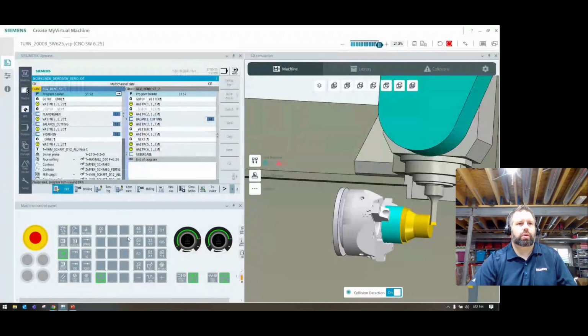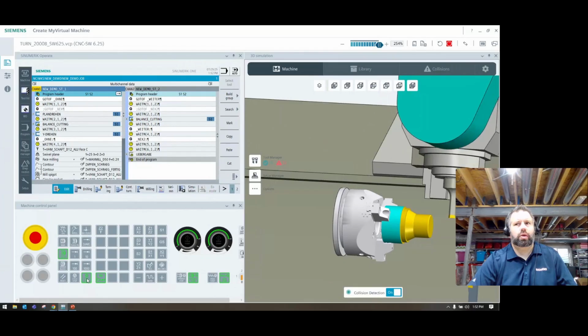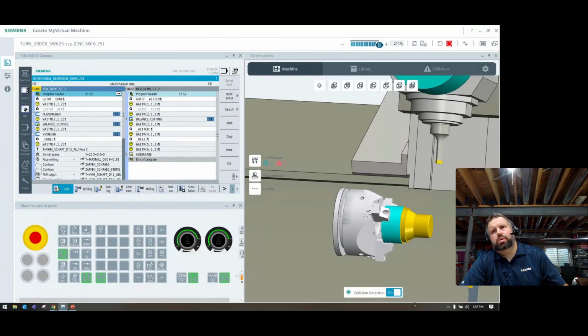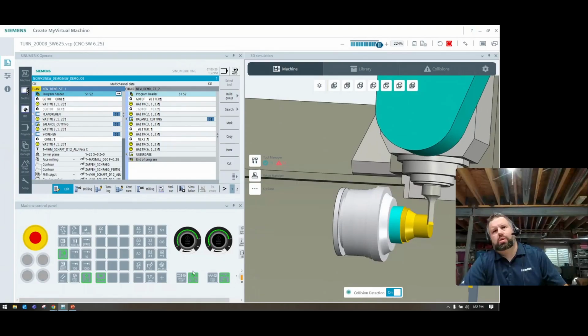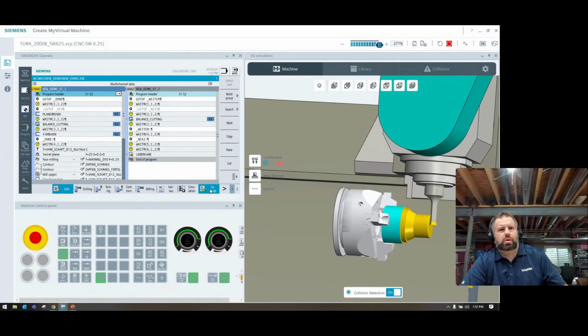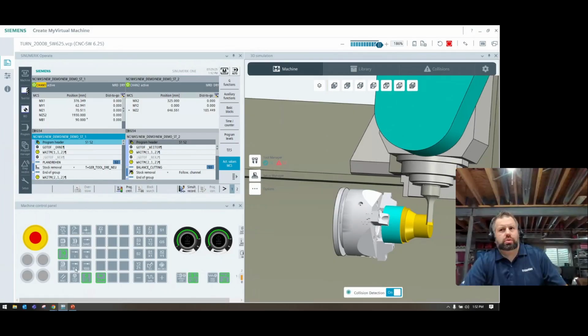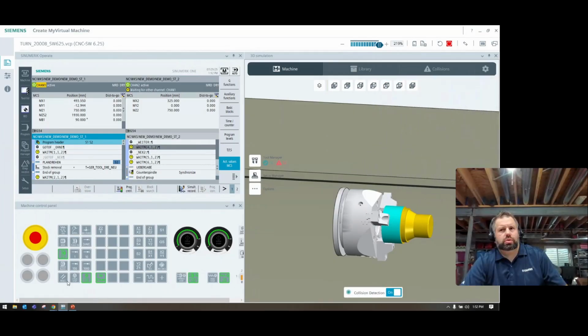While you're pulling that up, certainly some of the things that come to mind, boring head versus interpolation turning: think about the motion or the tool path and the chip load. It's really the same, very, very similar. One of the things you'd be somewhat limited by, unless you had one of those high-end programmable positionable boring heads, is how do you do a contour with a boring head?